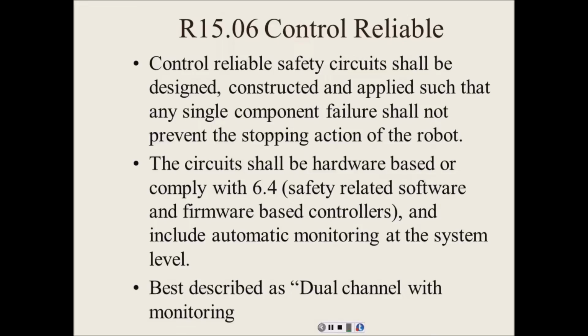It's not 1, it's 2. They're just operated by the same actuator. For each set of switches, we have a different electronic circuit. So there's 2 electronic circuits monitoring these e-stop and these safety devices. So if one electronic circuit fails, then the other one's going to pick it up, right? You understand? So your e-stop circuit and your safety circuits, these are what we call control reliable.